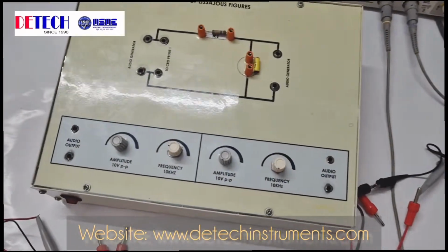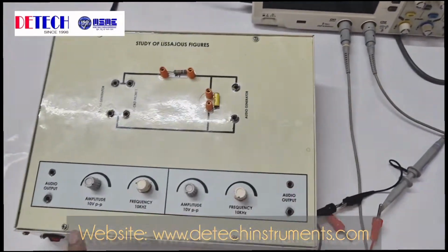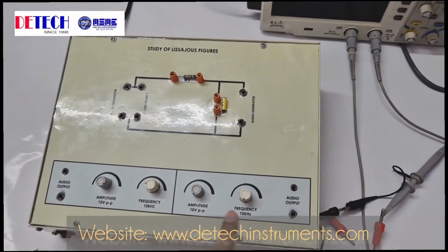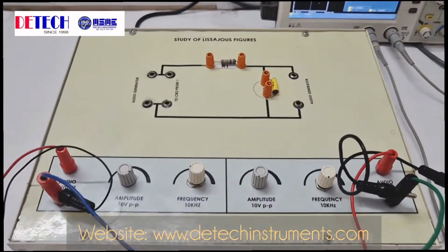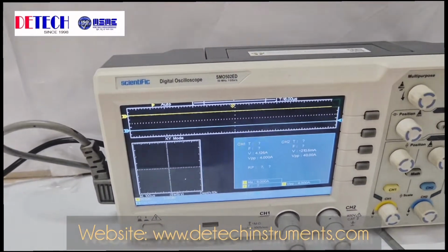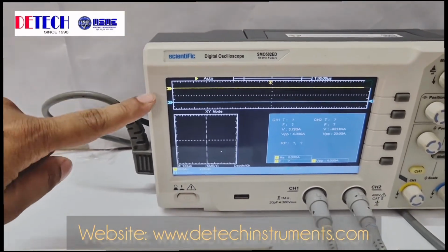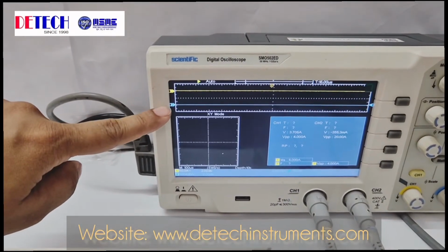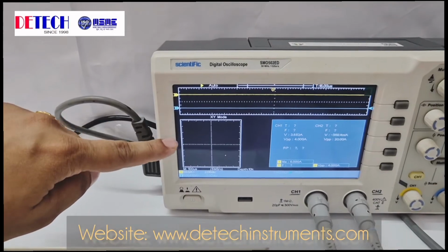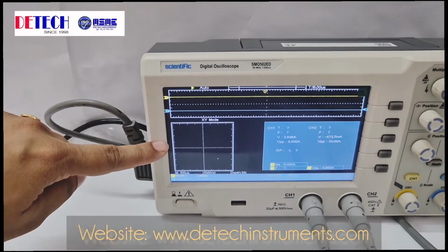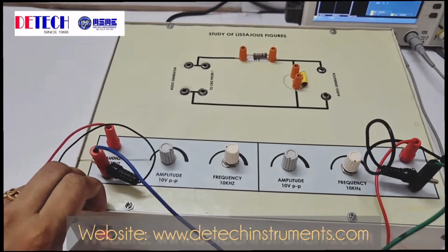So we will just simply connect the first channel of the DSO to the audio output and the second channel will be connected to the second audio output. We have switched on our kit and I've set the screen in such a way so that we can see both the input waveform and the output waveform. This is the channel 1 and the channel 2 signals, and also the XY mode we can observe at the same time. So now let us switch on the kit.